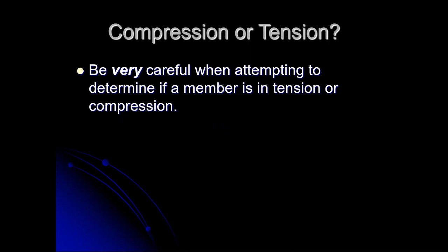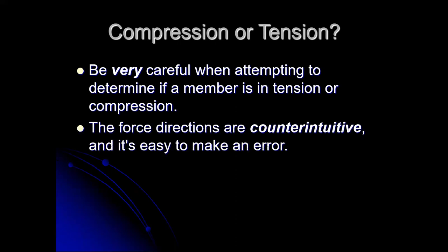So even though to squeeze a spring down, you'd have to push in, you're pushing in because your hands are being pushed apart by the spring. So we have to be very clear about what we're looking at. When we're looking at the supports, the forces are exactly opposite what you'd expect them to be, because we're looking at it through the mirror of Newton's third law. So the force directions are counterintuitive.